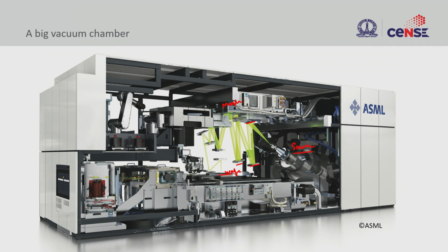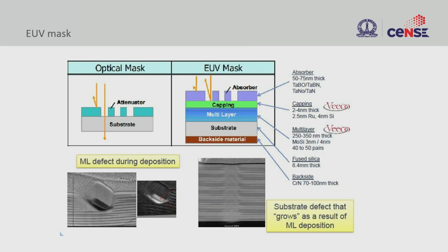At the same time, they should be in a chamber. That is the reason why all these challenges, including source stability and alignment stability, the mask technology and the resist technology, are still delaying extreme UV from hitting the production scale that is required.